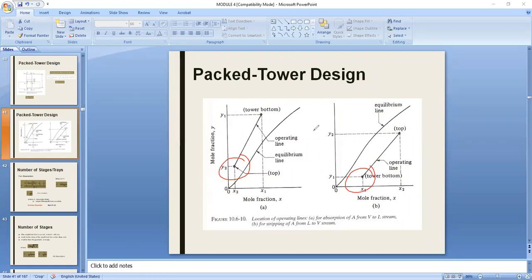So if you're given a curve, just like in this one, what particular slope will you substitute for the M? You will substitute the slope at the dilute end. In that case, you will just have to approximate. What you do if this is given is actually project this part on the curve and determine the slope in this part of the curve. If you're given a table of values for x and y, then you just determine the corresponding slope at this particular point for your x and y.